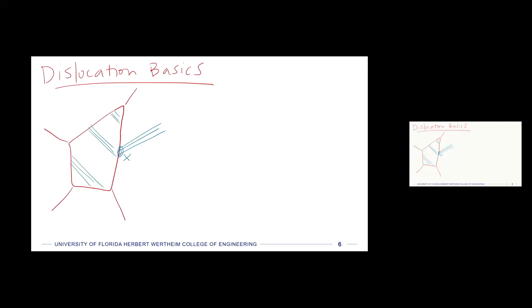So when this happens, and when this was first studied in the lab, they polished a surface to be very, very flat, right? As atomically flat as they could get it. And let's say it's something like single crystal aluminum, right? And so they know that in this aluminum, the crystal structure is all oriented. It's a single crystal, so everything should be oriented the same direction. And so then if they have an atomically flat surface, and then they apply some shear stress to it in some direction, then some of the material will actually start to pop up in little bands, right?